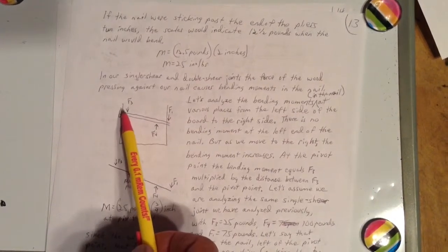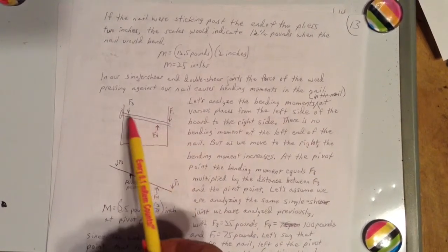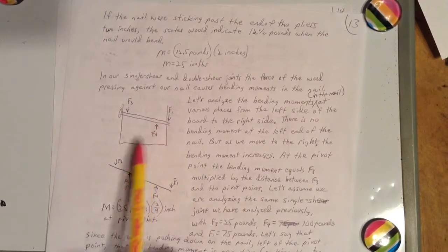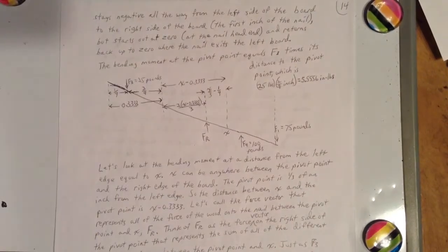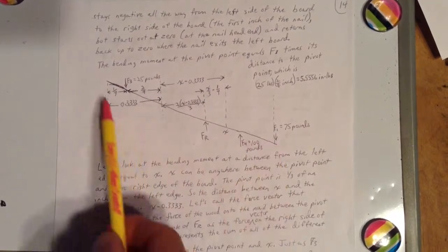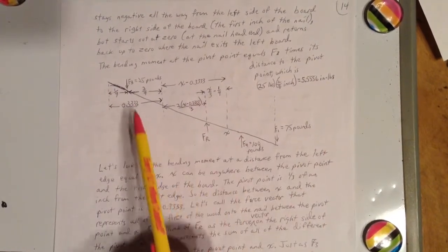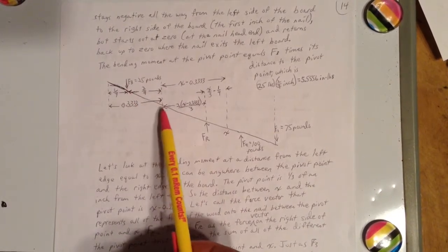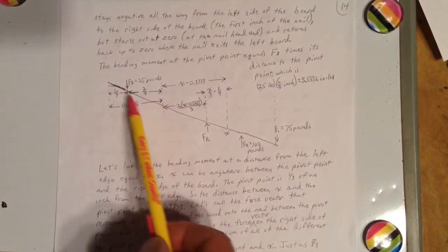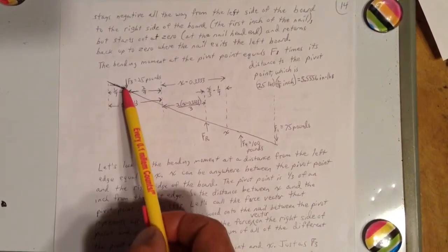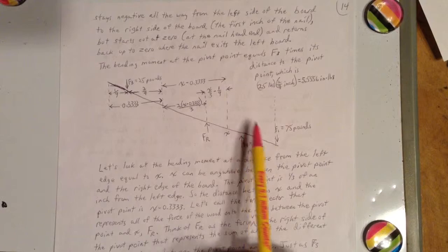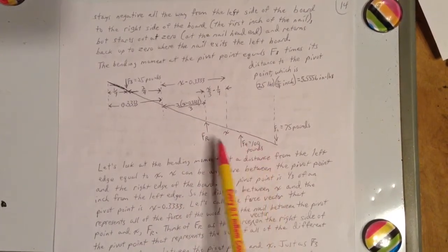But there is a bending moment all along in between here, and it's greatest at 2/3 of the way across, right along in here. Okay, so here's a line I've drawn. It represents the whole 1 inch from the left edge of the board to the right edge of the board. There's our F3. Here's where the line goes up. Here's our pivot point. Where the line goes up, that's all the stress between the wood and the nail that gives us F3. On this side of the pivot point is all the stress between the wood and the nail, which gives us our F4.